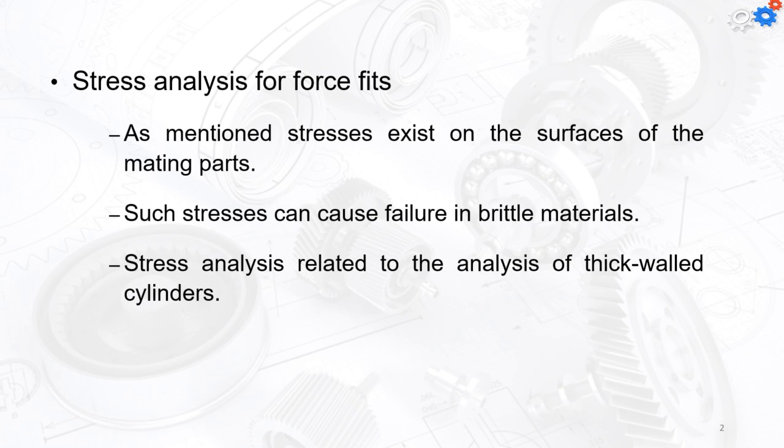So, an example, just a definition about the stress analysis for force fits. As mentioned earlier, the stresses exist on the surfaces of the mating parts. Just imagine that we have a shaft going inside the inner ring of a bearing. If we have a high interference ratio between the shaft and the bearing ring, then we're going to have higher stress imposed on both the shaft and the ring, and then the ring will transfer it to the rolling part of the bearing, and this will damage it.